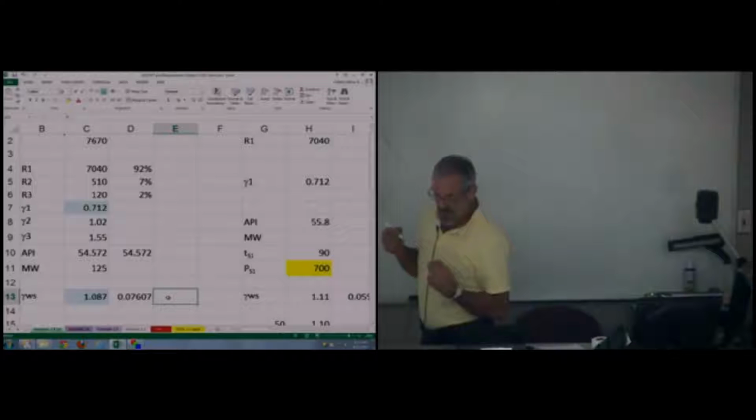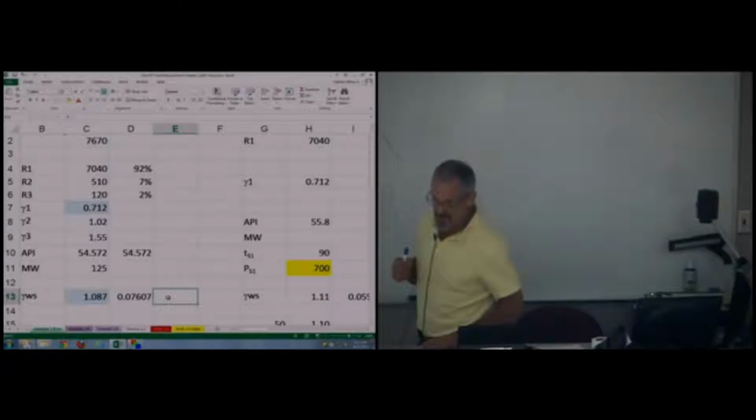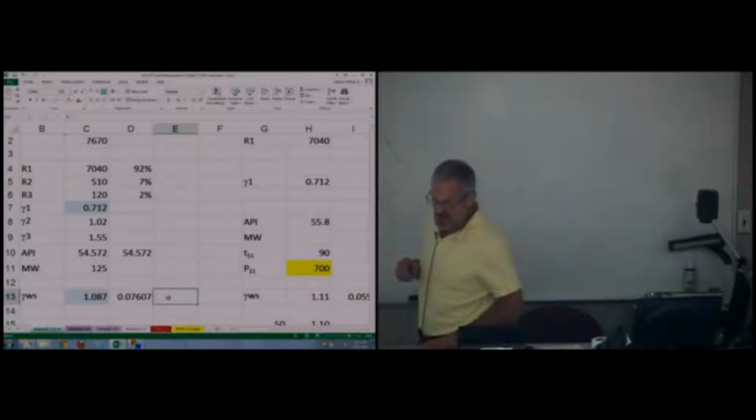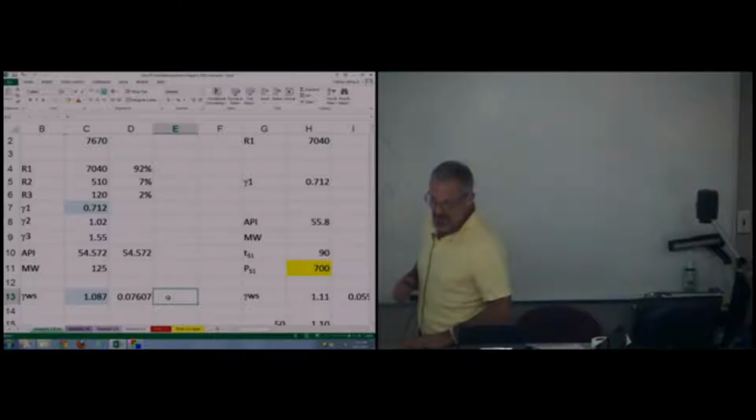I made my statement a little bit simplistic when I said if you have a linear trend, then bam, you do have your gradient. If you have a curve, then it's a little bit harder, but the gradient would be the tangent of that pressure-depth plot anywhere. The way to do it is do a polynomial fit of it and then take the first derivative and you should have the slope everywhere.